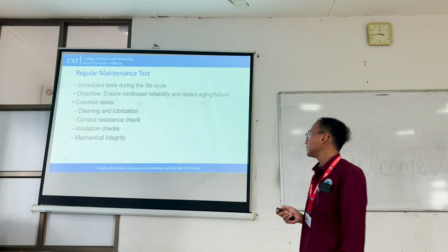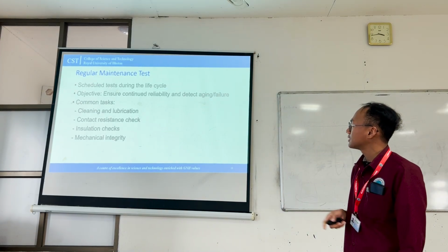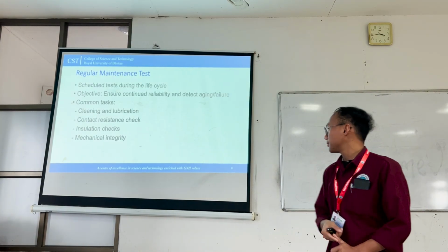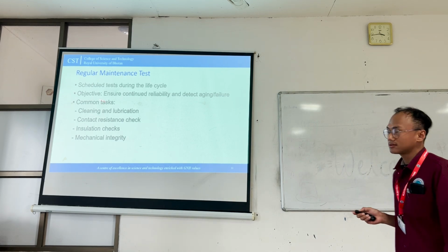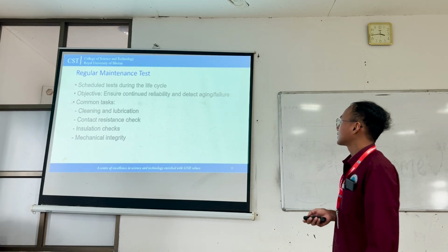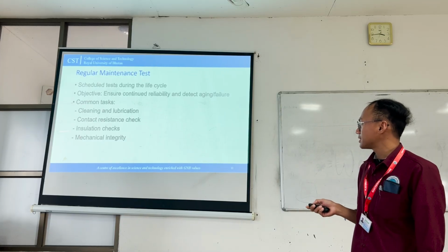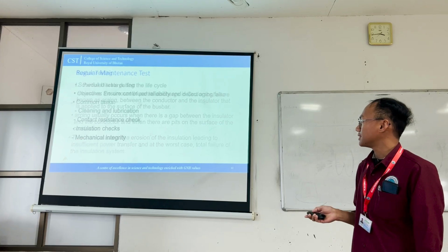Now, lastly, regular maintenance test. This is a scheduled test during the life cycle of the equipment, for isolators and busbars. This is mainly to check the continued reliability and detect aging and failure. This includes cleaning and lubrication, contact resistance, insulation checks, mechanical integrity.